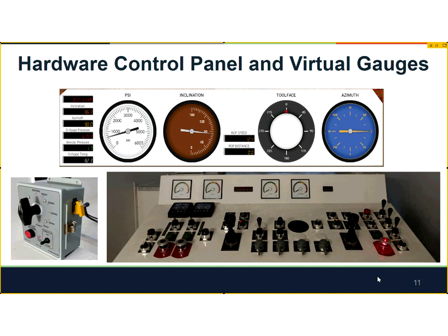And then there's all types of kind of presets that they can use to make sure that they don't exceed a limit in terms of the maximum torque or force that they want to apply. And then these are the hardware gauges that we use so they can look at the amount of PSI that they're putting into the hydraulic system that they're seeing as they're working.